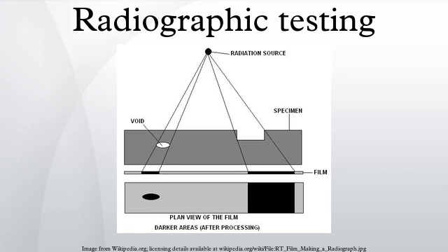Neutron radiographic testing is a variant of radiographic testing which uses neutrons instead of photons to penetrate materials. This can see very different things from X-rays, because neutrons can pass with ease through lead and steel but are stopped by plastics, water and oils.